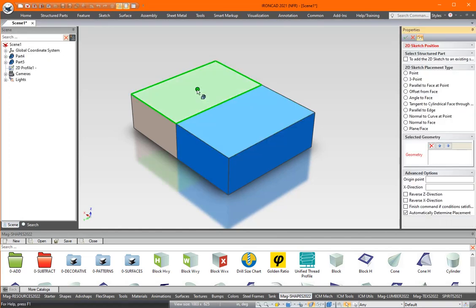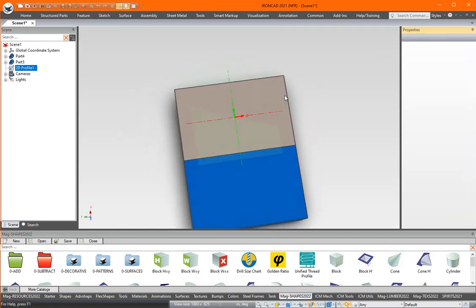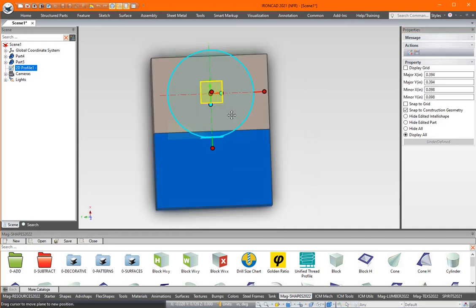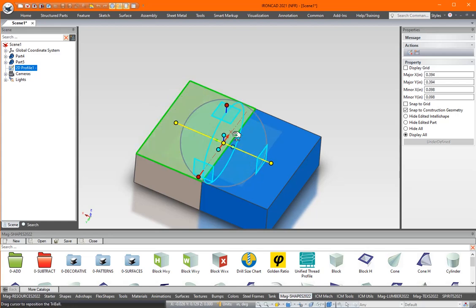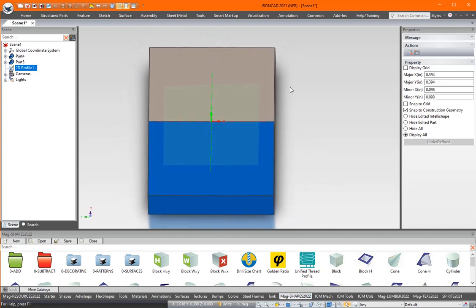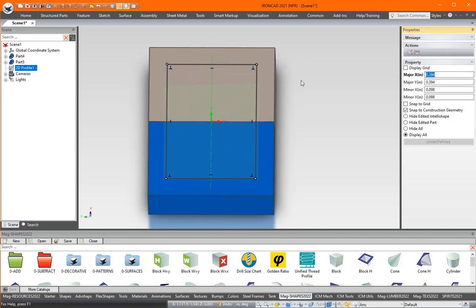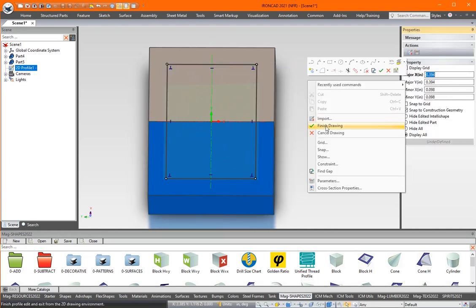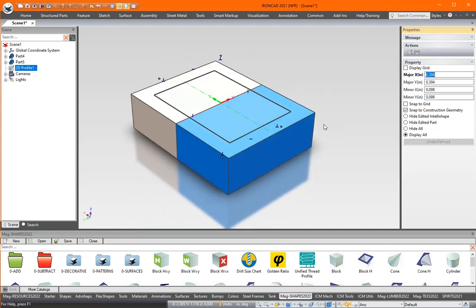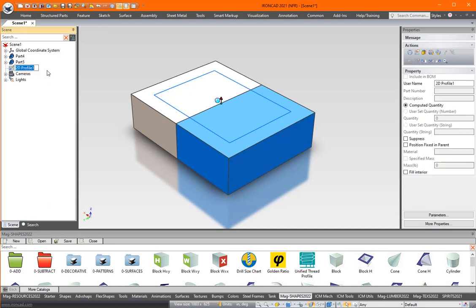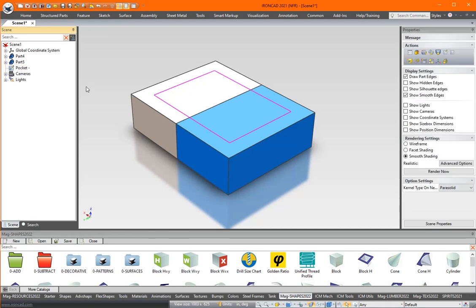and I'm just going to put a drawing surface right there. Okay, and we can move the center of it if you want. This is just more or less housekeeping. It's not really necessary. And now I'm going to draw a center rectangle. Just let's say that's about the pocket size. Again, just showing the abstract, not worrying too much about dimensions here, and finish that sketch. So now we have a sketch there. I know it's going to be linked, so I'm going to just give it a name. Let's say pocket.